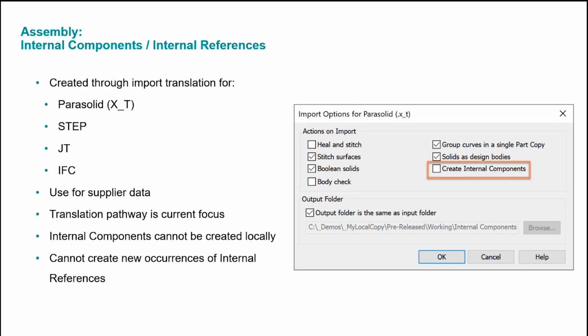Internal components are representations of the model structures in Solid Edge, and they contain all the geometry and structure of an assembly within a single document. With an internal component structure, the geometry, that is, the design bodies, the construction bodies, the sketches, reference planes, coordinate systems, and PMI for multiple components and product structure, are stored at the assembly level, without the need for additional files and links.